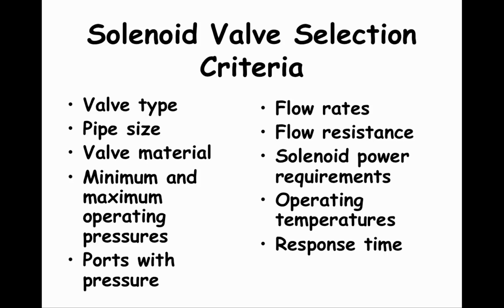What pressures will the valve be operating at? Note that some valves require some pressure on all lines so that the valve returns to its de-energized state when de-energized. Flow rates and flow resistance values are important too. Solenoid power requirements, duty cycle, and temperatures are things to consider as well. And if timing or speed is important, what is the valve response time?